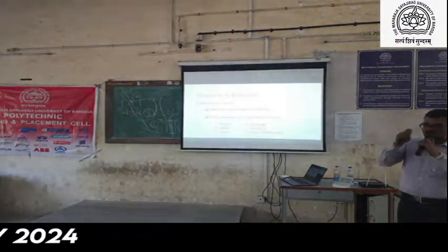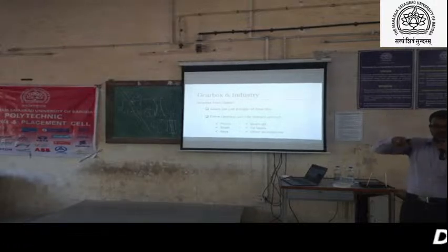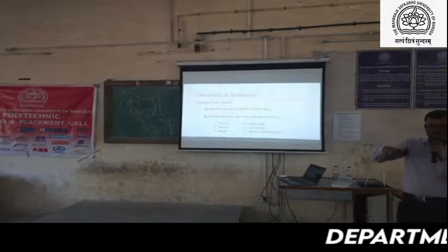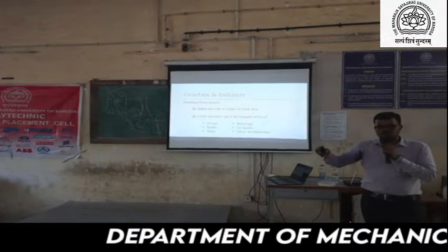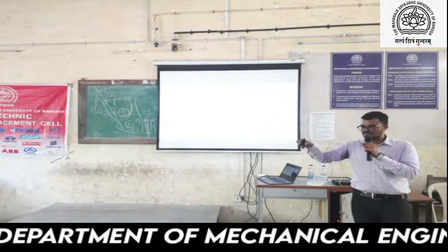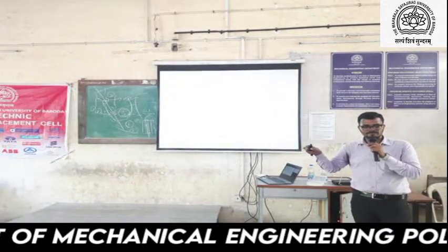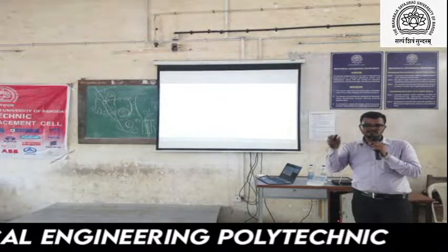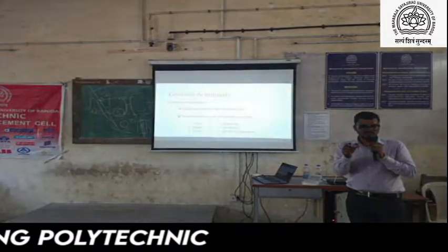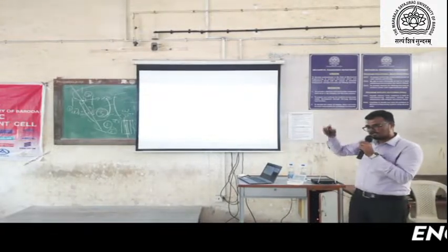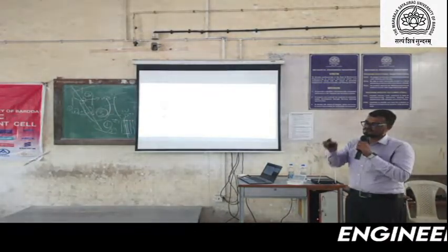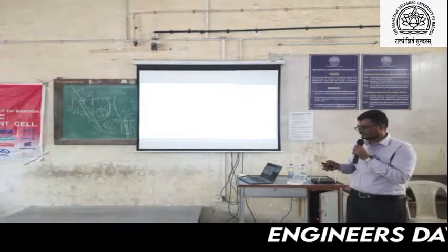Why? The pinion or gear will move slightly. At that time we need to arrest that movement, so we use a dummy component. That dummy component is called a DP, distance piece, or you can directly say spacer. You are arresting the space, so it is called a spacer. All other components will be less than the gears or gearbox.